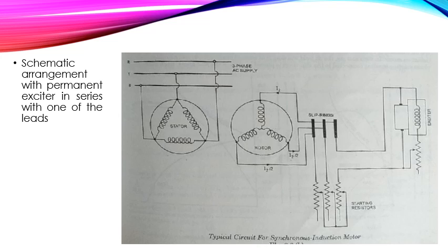Means what, here the features of two machines are combined. For power factor improvement and constant speed it is acting as a synchronous motor, and for variable speed, low starting current at starting, and high starting torque, it will be acting as an induction motor, right? So the features of two machines are combined.